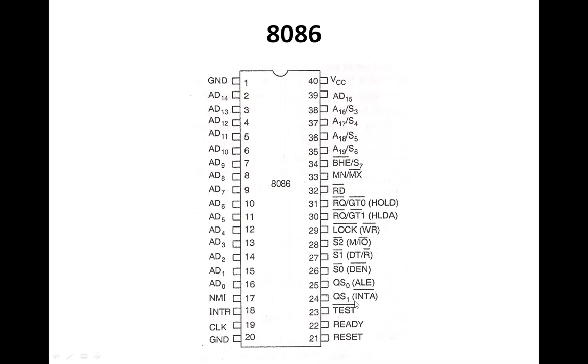So whenever any device wants to interrupt and activate a certain subroutine, called a service subroutine, that subroutine is written somewhere in the memory and has a certain address. So while acknowledging the signal, the time has come to place the address of that subroutine on the bus. So it is the pin which normally gives the acknowledgement of the interrupt signal received from an external device.